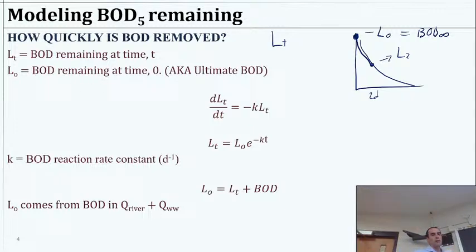So that means that if we were to take that 2-day measurement, that would probably be the exact same thing, or what we would notice is if we measured the difference between here and here, that would be a 2-day BOD test. How much oxygen demand was exerted in 2 days. But again, typically we measure in 5 days. So what we would do is we would measure the 5-day BOD here and the 5-day BOD here, and we could get some numbers there.